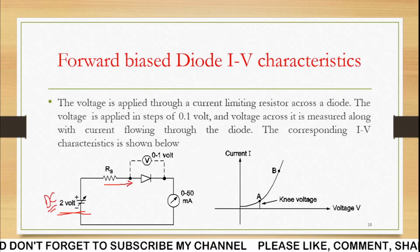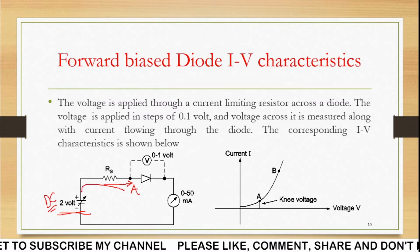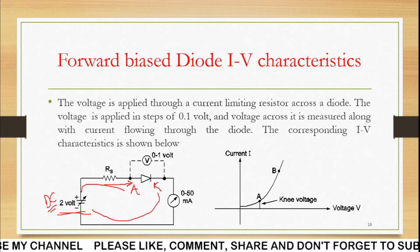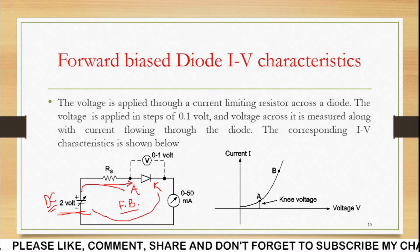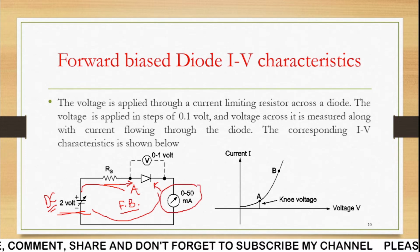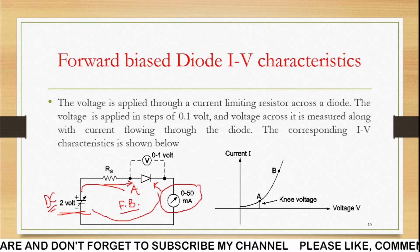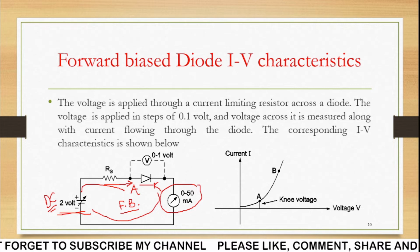This is a diode where the anode terminal of the diode is connected to the positive part of the battery and the cathode terminal of the diode is connected to the negative of the battery, making this circuit forward biased. And here is a current meter that is going to measure the current when the voltage is varied from 0 to 2 volt in this particular diode.